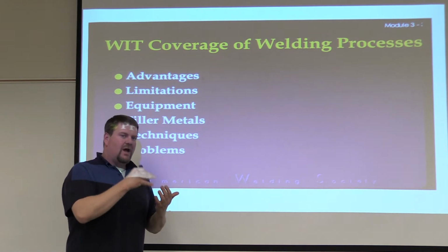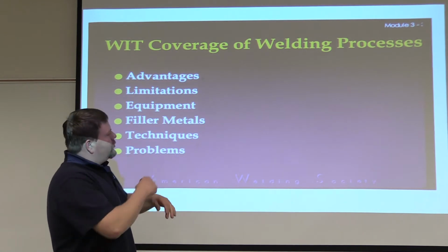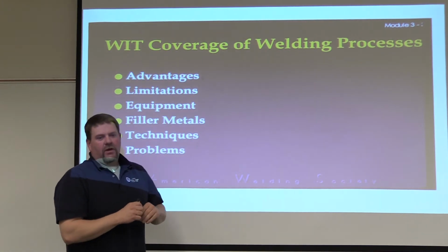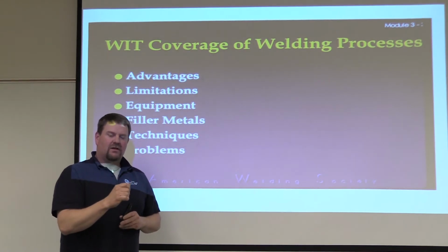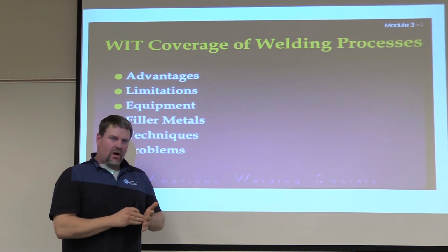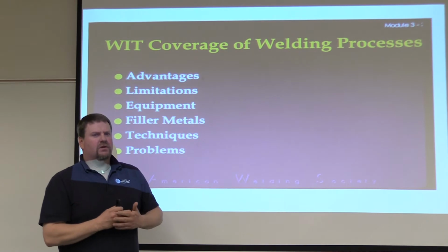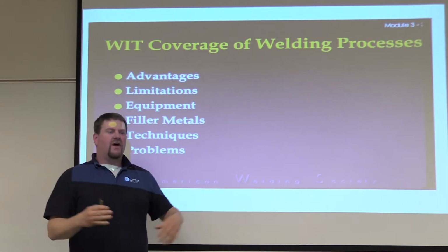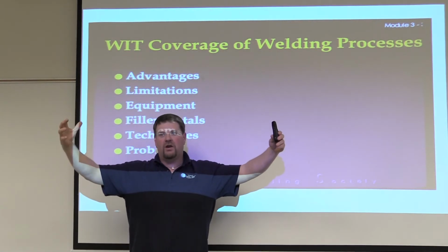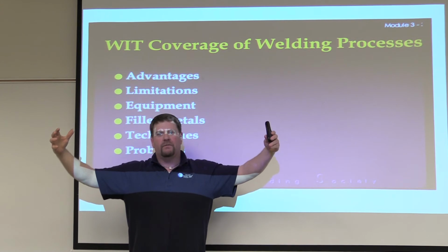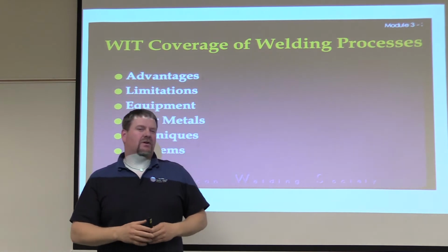And then we kind of go up and down, which causes some problems, which we'll learn more in the metallurgy portion of it. But 3D printing of it, doing it at that exact point, you don't have to take it up to 3,000 or 4,000 degrees to get it to have that tensile strength or that yield strength that's required. It was a game changer. Okay, the grain structure can be controlled, the heat affected zone can be controlled, much different than subtractive manufacturing, which might be one huge piece of aluminum, which costs a ton of money to foundry and pour, and then also turn around and machine it all out, and there's a lot of wasted material in there as well.